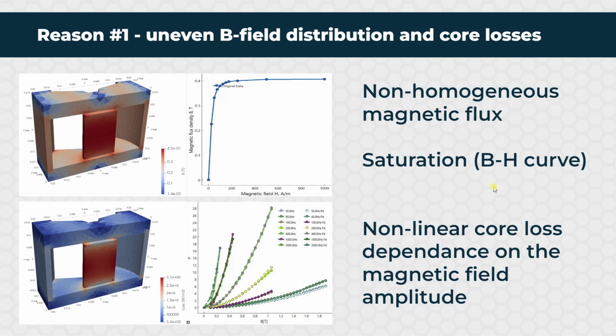Let's talk about the main reasons why 3D FEM is a great tool in your toolbox. It should not be the only tool, but it should be one of those tools that you will use to design components. And the first reason, as I see, is that very often the assumption that magnetic flux is uniformly, homogeneously distributed within the core does not hold true.